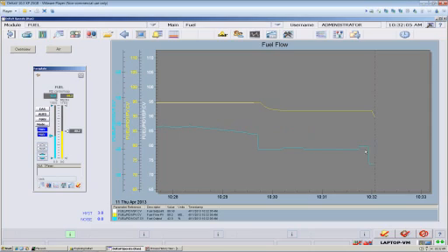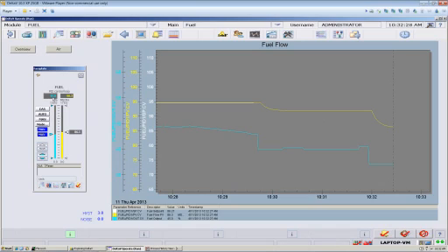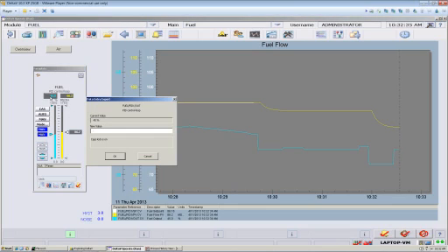Now in this case, anytime I changed direction, I was moving more open, more open, more open. Now I made a change that's more closed. Anytime I changed direction, in this example, if my change is less than 3%, I'm only working in that sloppy area. I'm not affecting my flow. But as soon as I get across that area, then I do see a change.